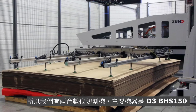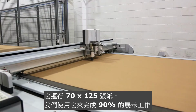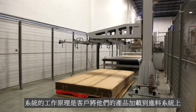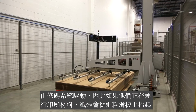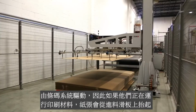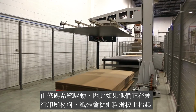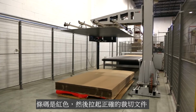So we have two digital cutters from them. The principal machine is a D3 BHS 150, and it runs a 70 by 125 sheet, and we use that for 90% of our display work that goes through there. How the system works is the customer loads their plain product on the feeding system, and the system is driven by a barcode system. So if they're running printed materials, the sheet is lifted from the feeding skid, the barcode is read, and then it pulls up the right cut file.